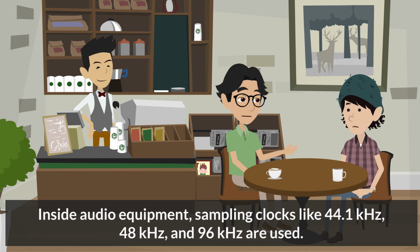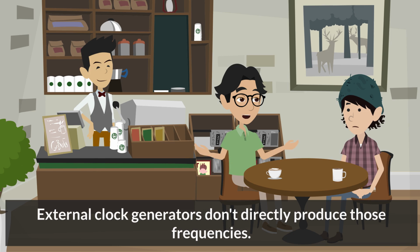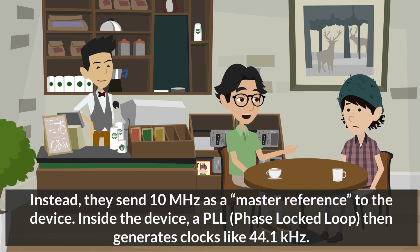Inside audio equipment, sampling clocks like 44.1 kHz, 48 kHz, and 96 kHz are used. External clock generators don't directly produce those frequencies. Instead, they send 10 MHz as a master reference to the device. Inside the device, a PLL, phase-locked loop, then generates clocks like 44.1 kHz. PLL?